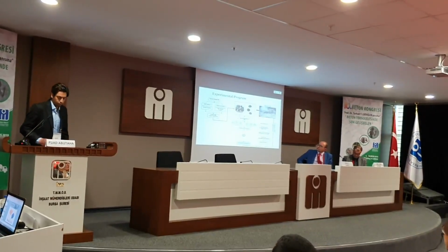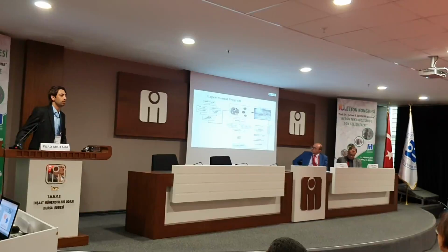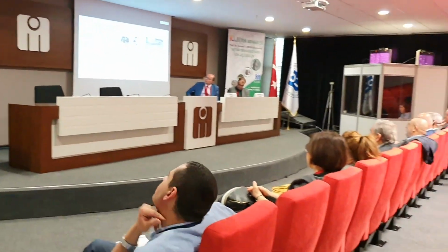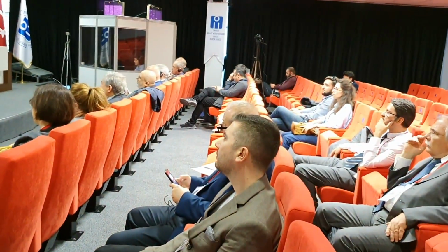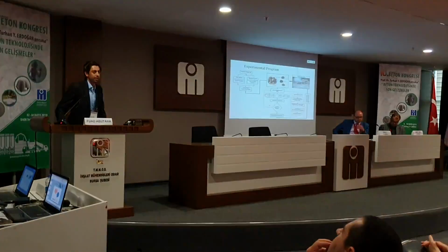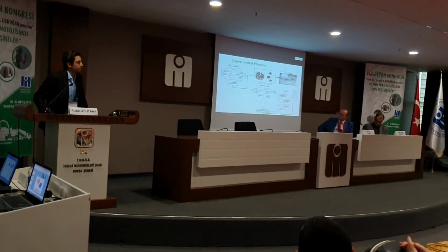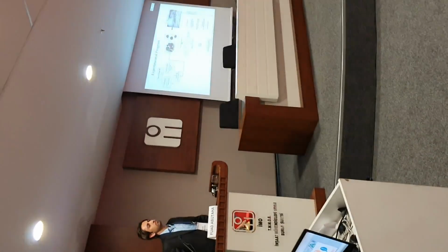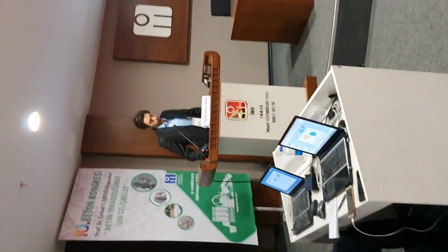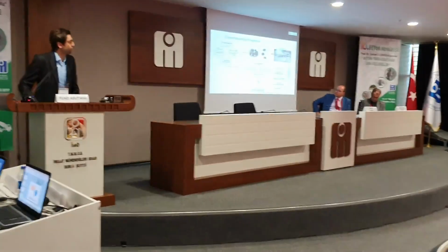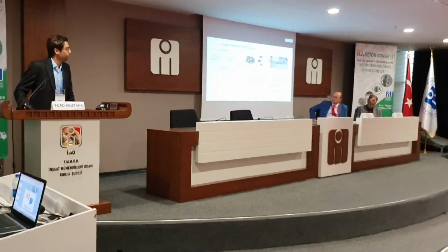So we have the same material as coarse aggregate, fine aggregate, and in powder form as a filler material. In the experimental program, we have two grades of concrete: a normal grade of 40 megapascal and a high strength grade of 90 megapascal. The replacement of the natural coarse aggregate with this waste material was conducted in both grades, to assess the effect of this waste material in different grades of concrete.